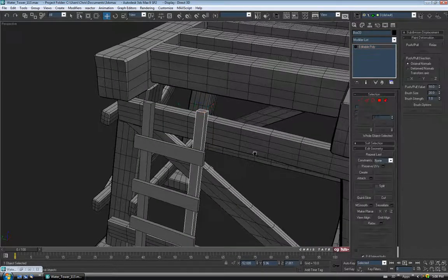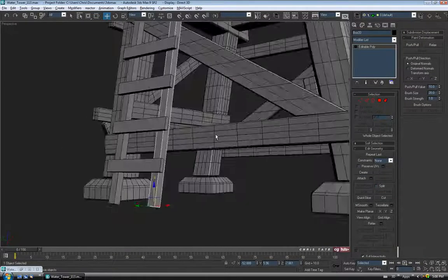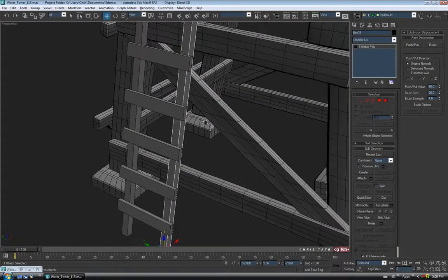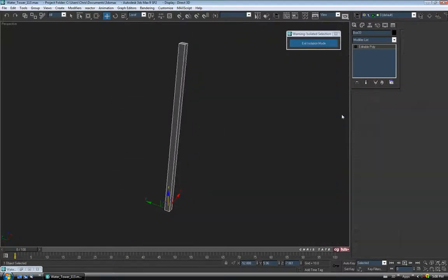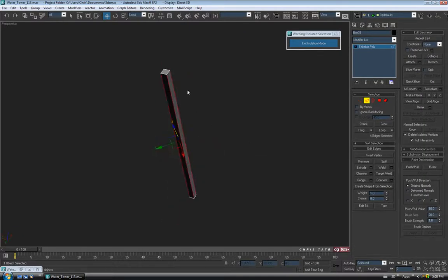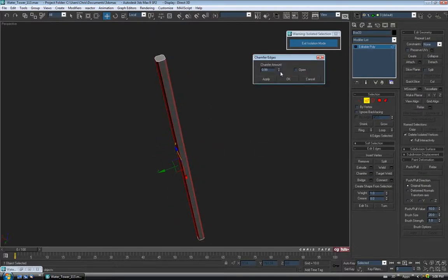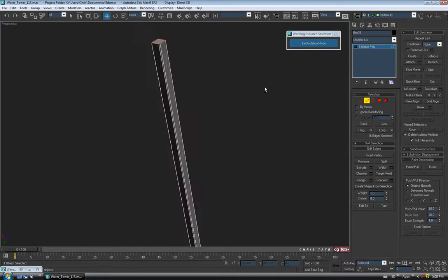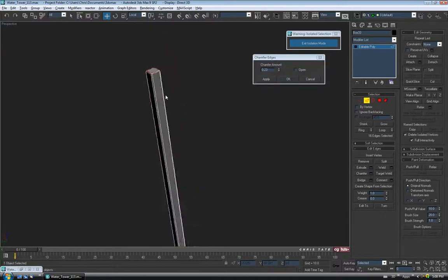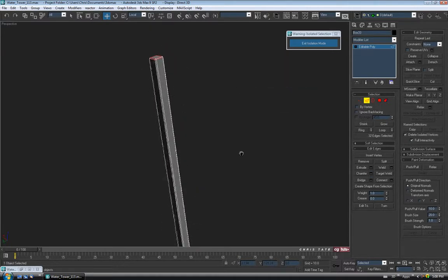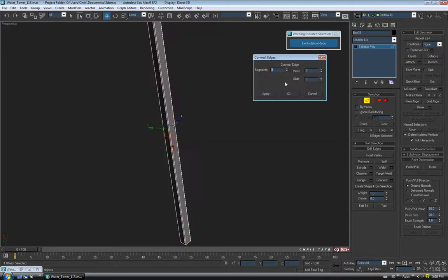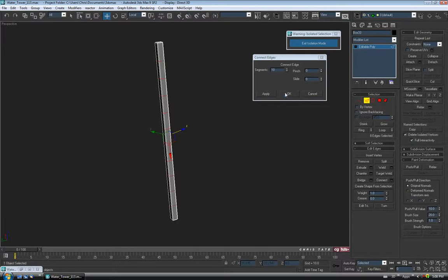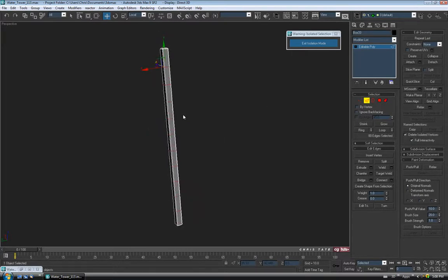Okay, and I think everything else is okay for it, so let's just subdivide it and chamfer down the edges. So go into isolation mode, grab our edges again. Alright, and I'll try to speed through this because I know it's getting repetitive. So we'll do it maybe around 0.23, say OK, invert, chamfer again. Alright, I might just leave the end at that, say OK, and then we'll add our subdivision here. Alright, let's do maybe like 10. Should be enough, so it's OK, and I'm going to add maybe 1 in the other 2 directions.